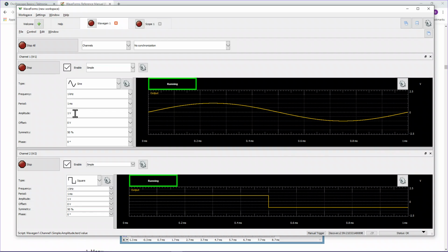That's because when we start dividing each major division into 10, 1 volt divided by 10 is 0.1, and the math works out pretty easily. So hopefully that'll give you a little bit of a start. And we've generated another signal, a square wave, from channel 2. Once again, we made that 1 volt per division. Both are 1 kilohertz. We're going to keep things simple.